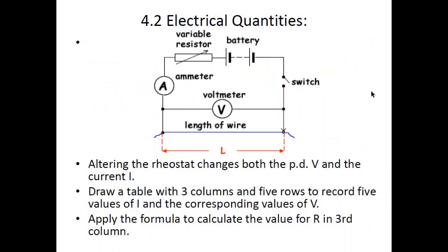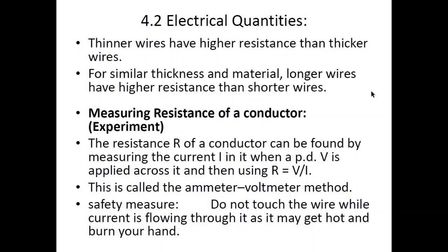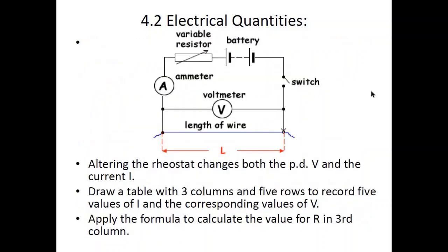When a conductor has higher resistivity and a current tries to pass through it, then it becomes hot, or its temperature increases. Now this is a supposed diagram of such a circuit that can be used to find the resistivity of a conductor. We use a battery that is connected in series with an ammeter and a variable resistor. A variable resistor is an electrical component which has a knob on it, and by moving that knob you can either increase or decrease its resistance.